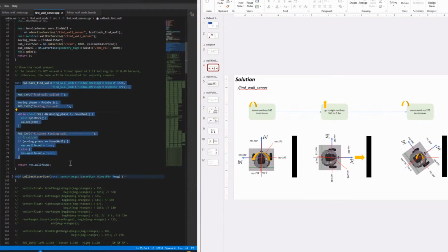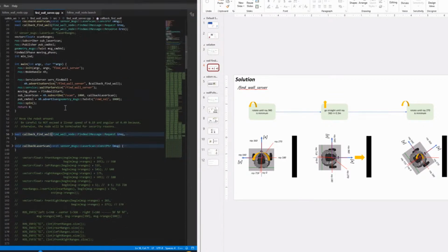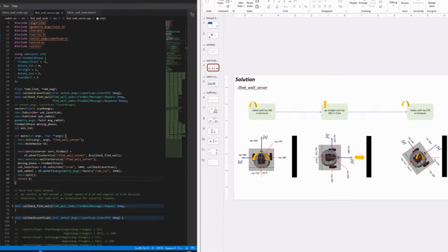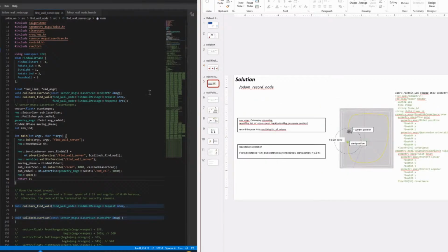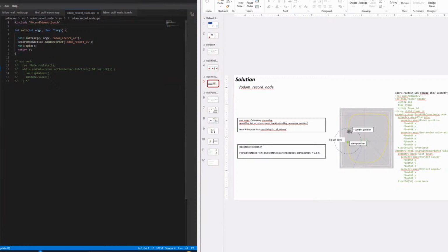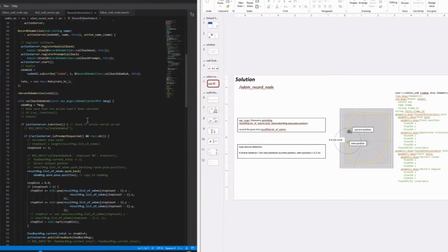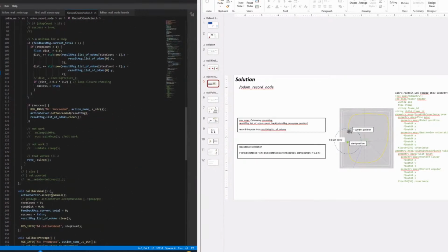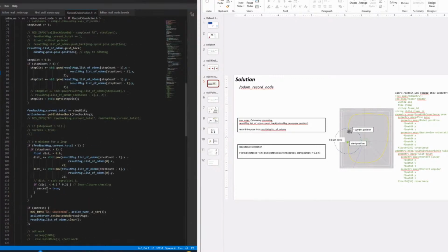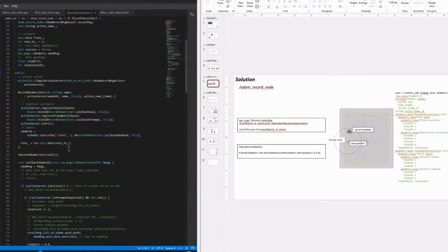Here is where it does the maneuver. Okay, I will move next to the action server that does the odometry record. I made the odometry record action server as an object to make the code easier and cleaner, with an object-oriented design. What the action server does here is make a subscription to the odom topic that receives the information from the odometer of the robot.